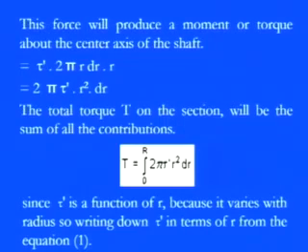Once we have the force, this force will produce a moment about the central axis to resist the applied torque, because when you apply the torque, these shear stresses form. Due to the internal reactions, they always set up a moment exactly opposing the applied torque, and that is why we call it the resisting torque, or the twisting torque.